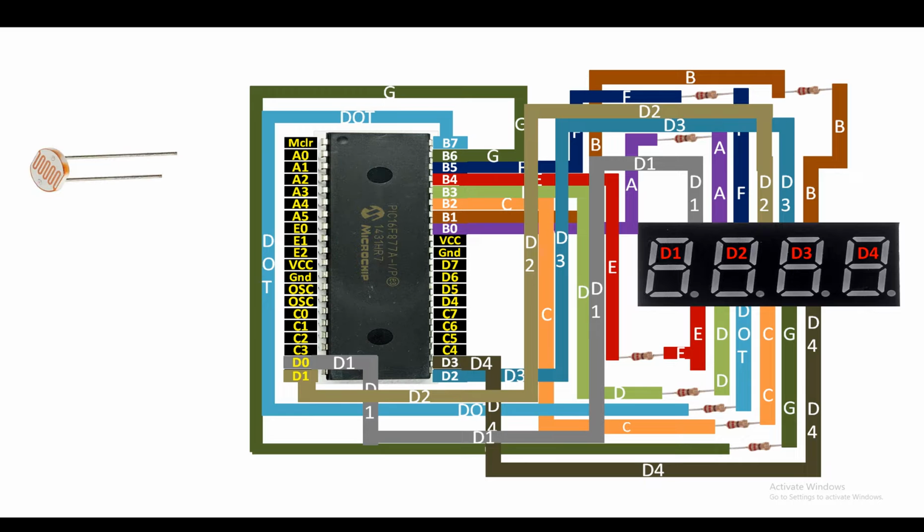Now guys, we have our LDR. Now we have our LED. Now let's connect these two as well. For the LDR, you know that one pin is the value, the other pin is the 5 volt. You can shuffle these two pins, it doesn't matter. For the LED, the shorter pin is always the ground and the longer pin is the 5 volt pin. Remember that you can never shuffle these two pins in an LED. If you shuffle them, then this LED will be burned. So the 5 volt or power pin is always the longer pin, and the ground pin is the shorter pin.